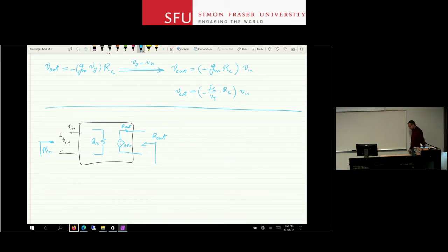The small signal resistance. If you connect the ohm meter there, you don't see that. And just convince yourself that you are not supposed to see it. Let's say if I tell you that the input resistance of this amplifier is 10 kilo ohms, and you put a multimeter there, you will not measure 10 kilo ohms. You should not. If you measure it, it's just a mistake, it's just a chance. Convince yourselves that you cannot measure that resistance with an ohm meter. Now that you cannot measure it with an ohm meter, we have to find alternative ways to estimate it, and you do that in the lab.